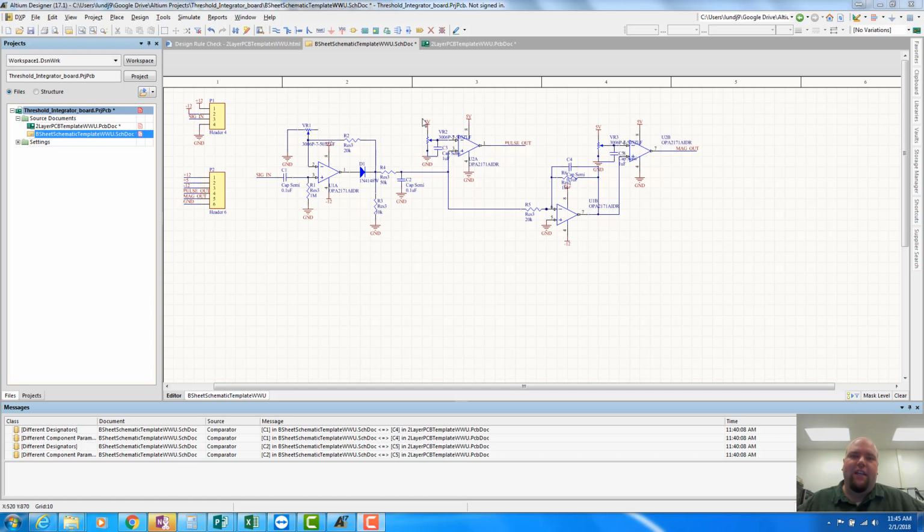There's better ways to do it, so we don't have to use an op-amp. We could use a voltage detector. A comparator would probably be a better way to do it. Probably running it through digital logic we should do, but it should work fine for this. It should work fine producing a digital signal. The op-amp that we're using has a pretty good slew rate, so it's going to be a fairly clean edge when it does this. It's not too much to worry about. But just note that maybe we should have added an extra Schmitt trigger buffer or something like that to clean this signal up.